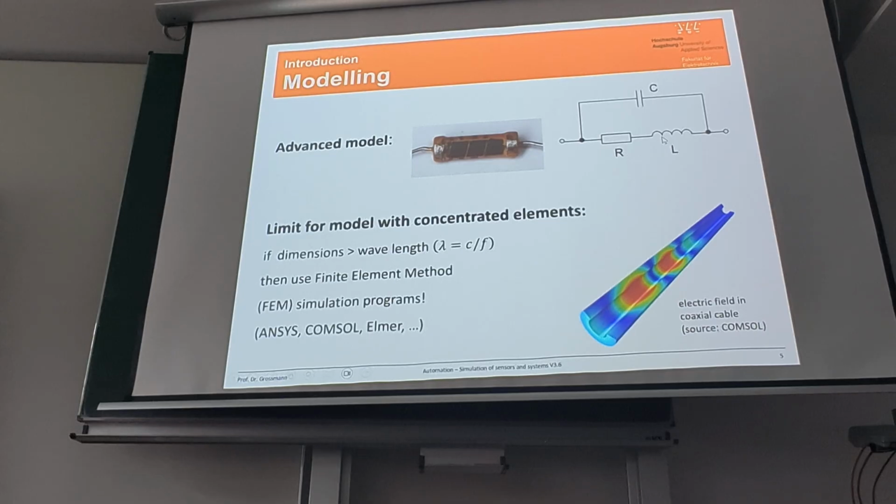But that's not all. You see something more here. On the left and right side, there are clamps, fat metal clamps. And these two clamps act like a capacitor. They're just like the plates of a capacitor. So we can model this with a parallel capacitance. And actually, it was the effect of this capacity that we just saw, because for higher frequencies, this becomes an ever smaller resistance in parallel. So the total resistance is reduced for high frequencies, and that was what we saw.